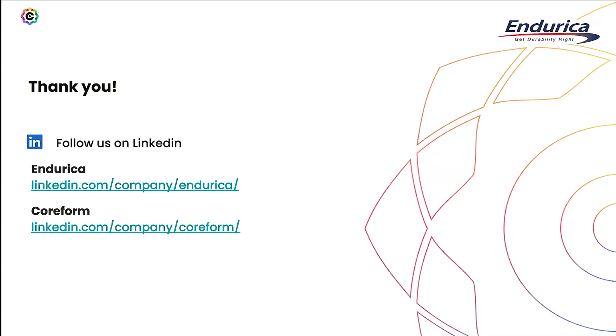Okay, the question from Dalen. I can see from the hyperelastic stress strain curve that the strain can be pretty high for rubber. What kind of strain measure did you use? Yeah, so the Endurica solver supports a couple different strain measures. And I believe we would have used nominal strain in this case. The solver supports nominal strain, we support log strain, we support Green-Lagrange, but I'm pretty sure we used nominal strain in this case. Old habit.